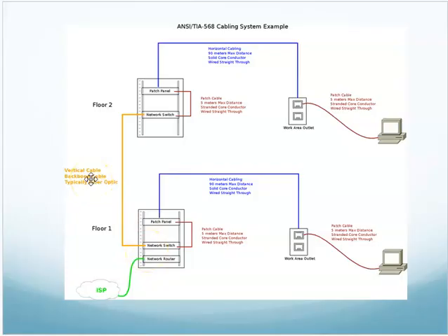That is for bandwidth, also for distance, and also because fiber optic is made out of glass. It's an insulator for electrical isolation. If we have an electrical short in this closet, it's not going to travel across this link to the other closet. So that fiber optic link is allowing us to do some electrical isolation.